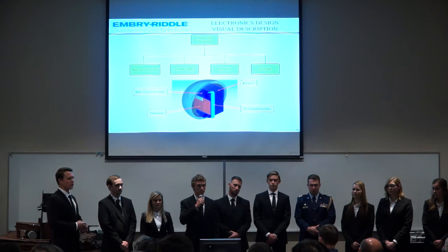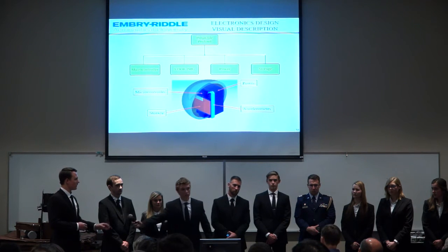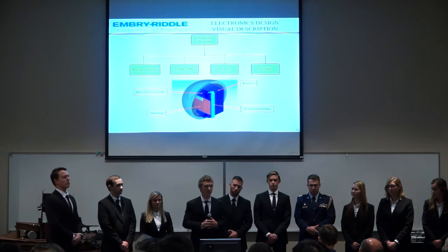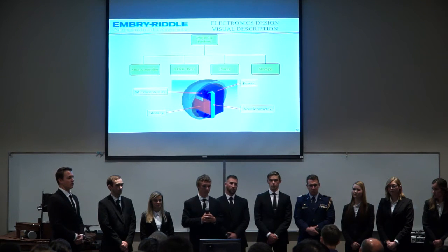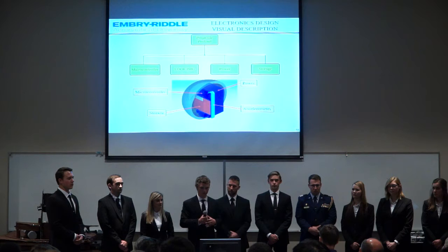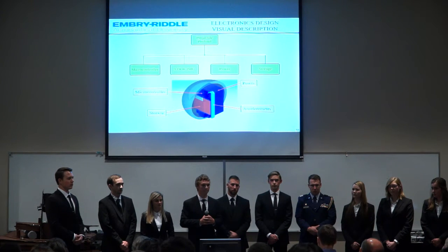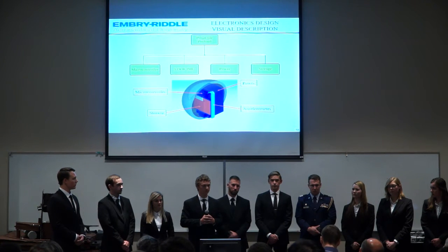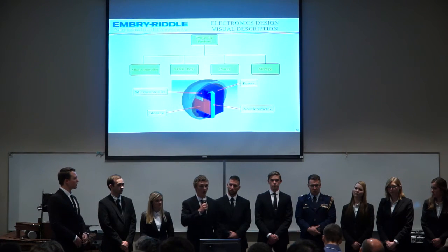A few other options you may want to consider too. You can pot using epoxy, which we've done before. It's messy, but it really protects it. And then you get really good information too because it's a rigid connection. I'm a little worried about foam because you may not have a rigid connection, so you may not get good data from it. Okay, that's all I have on that one.